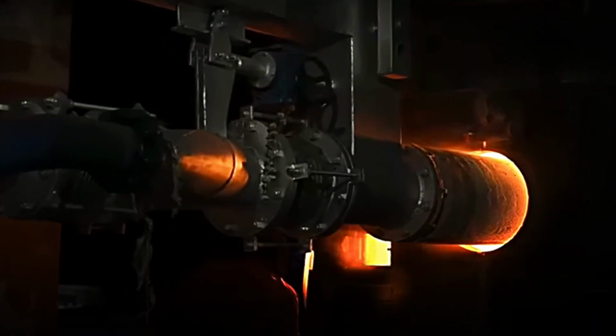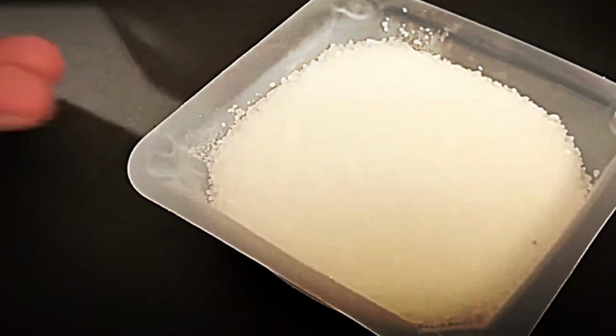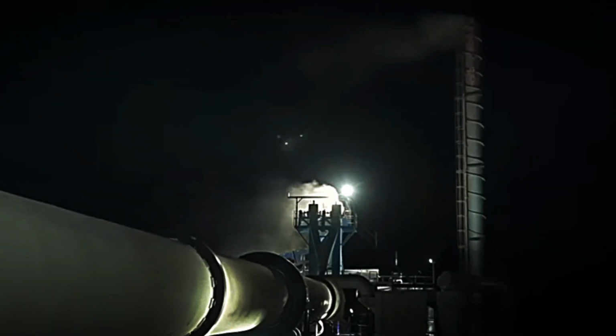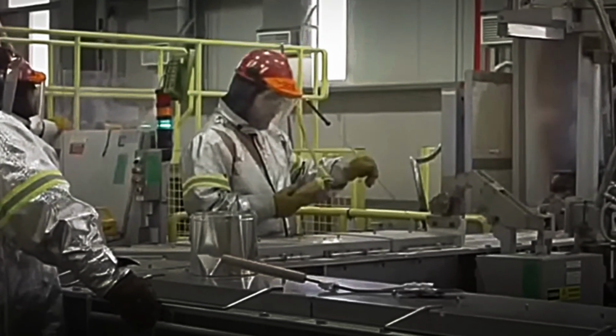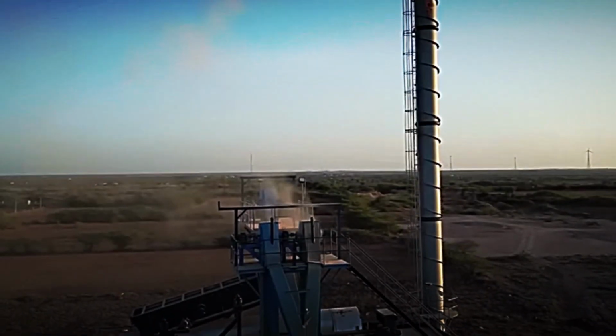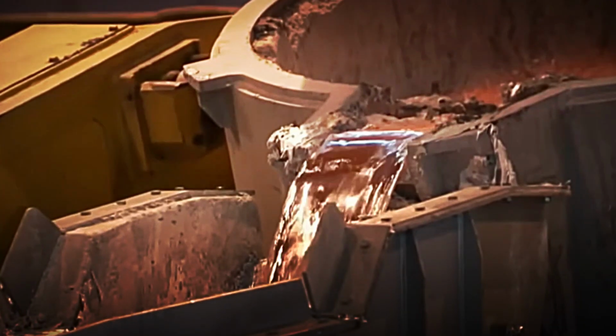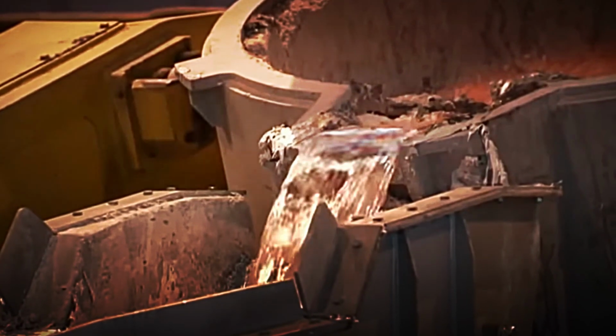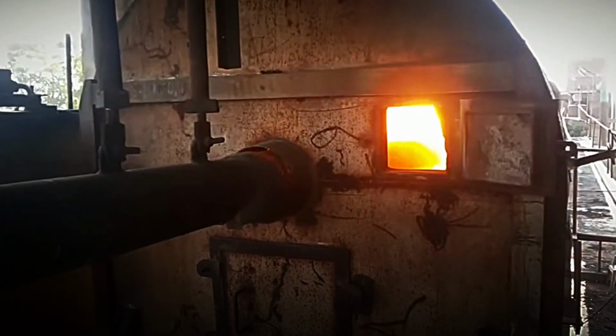Once the aluminum hydroxide crystals have formed, the next challenge is transforming them into a stable, useful material for the production of metallic aluminum. To do this, the crystals are introduced into calcining furnaces, large structures designed to withstand extreme temperature conditions and maintain a continuous process. During calcining, the aluminum hydroxide is subjected to intense heat that can reach 1,000 degrees Celsius.